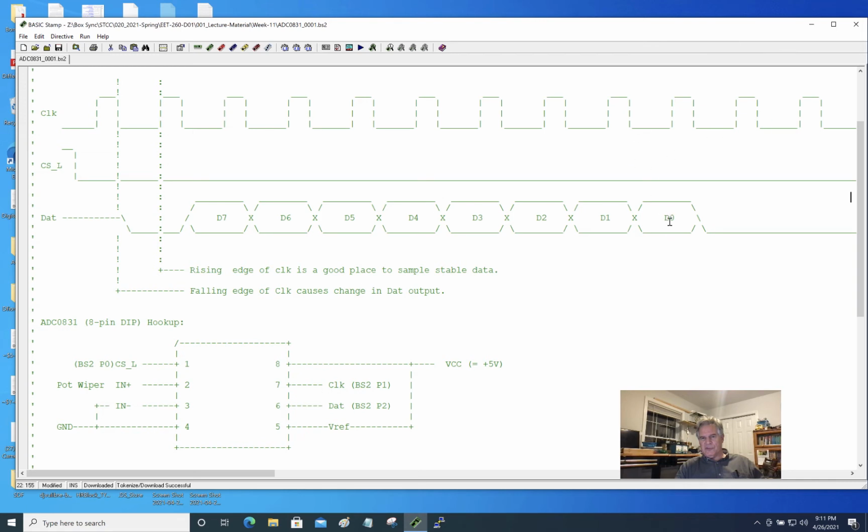And say, well, how do you get the last data bit here? Remember, we're not actually using this rising edge. We're timing off this falling edge to a time that's just before the rising edge. And so the microcontroller seems to do that. And that's all part of a special instruction in the Parallax P-basic language called shift in.